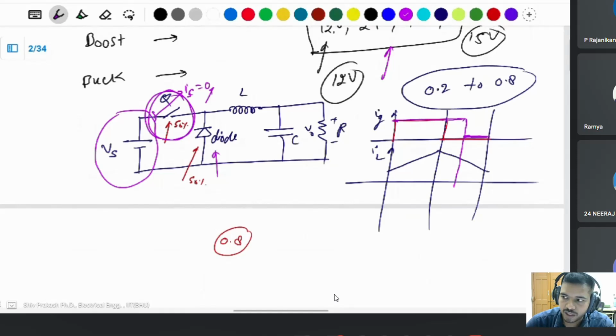If you learn about the buck-boost converter, the boost converter has a right half plane zero. It means it is a non-minimum phase system, not a minimum phase one. The zero is placed on the right half plane, which makes an overshoot come into your system for the boost converter. And the buck converter has the issue of ripple current on the input side. You should take care of this if you want to place any converter.